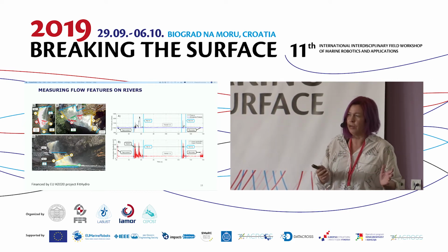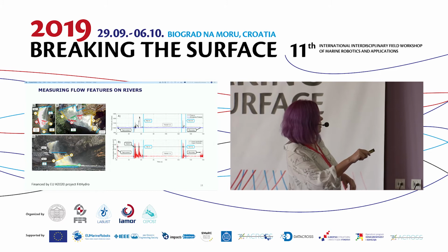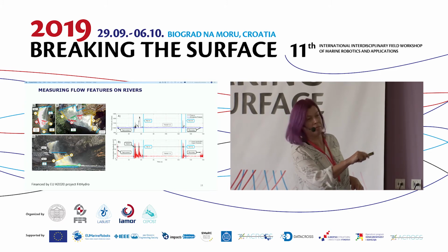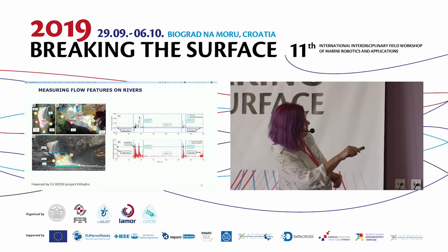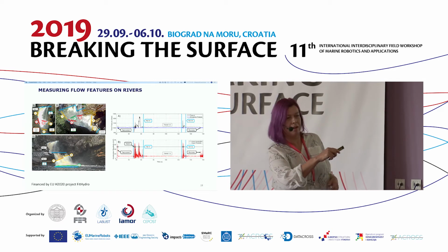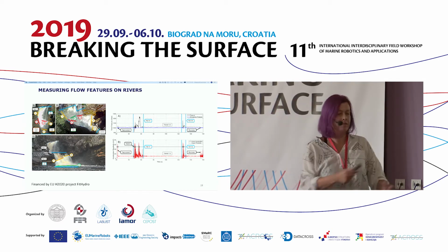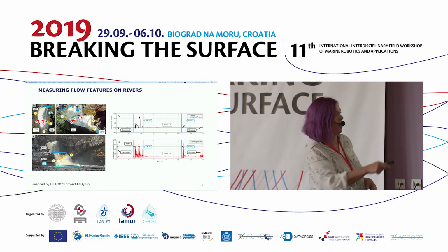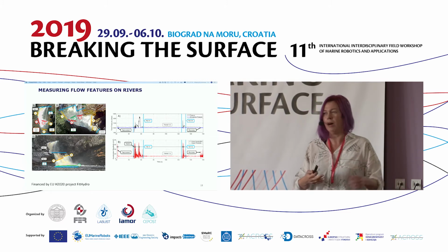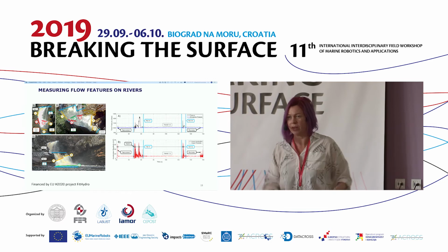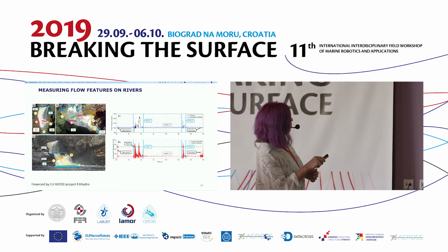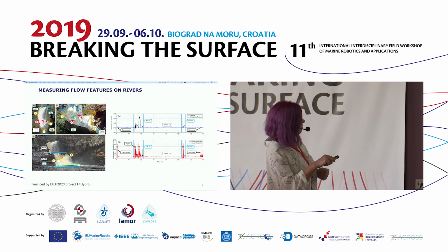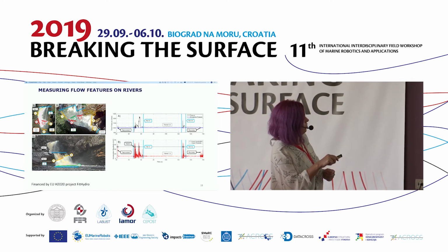Or if you want to do it in technical terms, then you have subcritical flow here, you have supercritical flow here, and subcritical flow here again. And looking at those things, you could say, okay, this is what river hydrodynamics calls a step riser, and there is another step riser, and between you have a chute. So this is how hydrology people characterize flows. And you know that this is true because you can see the flow here, and you have a ground truth.